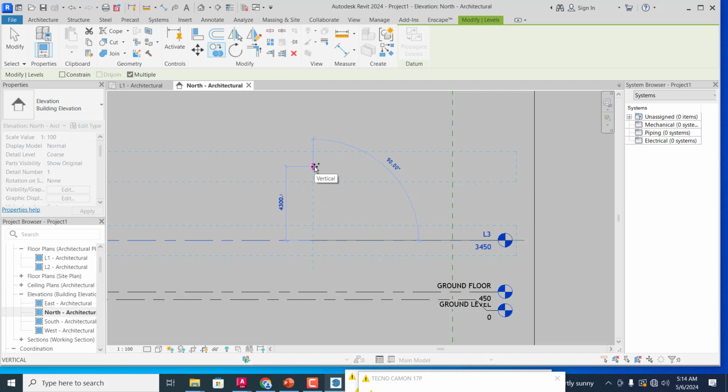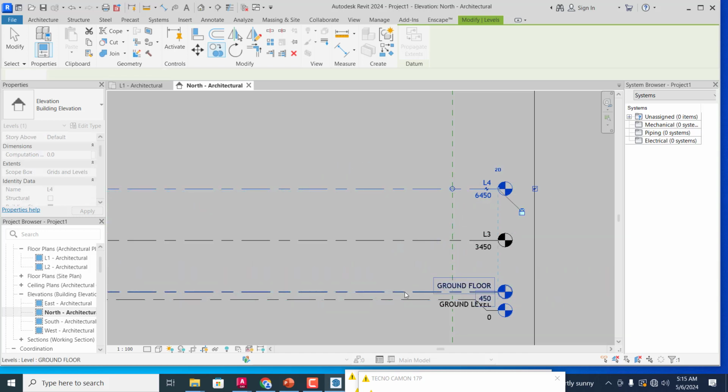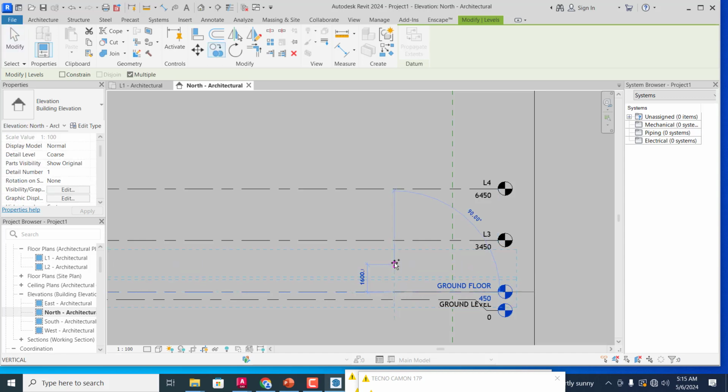And similarly, I'm going to copy again to the next level by typing the height, and I will specify 3 meters as well. So here I'm having my ground floor, here I'm having my first floor, here I'm having my roof level. Okay, so all I need to do now is to specify other levels like the landing level. You are going to see how I will use that as we progress. So I will click on this and I will hover my mouse up, and then I will specify the height for my landing level as 1,500, and I will do similarly for this.